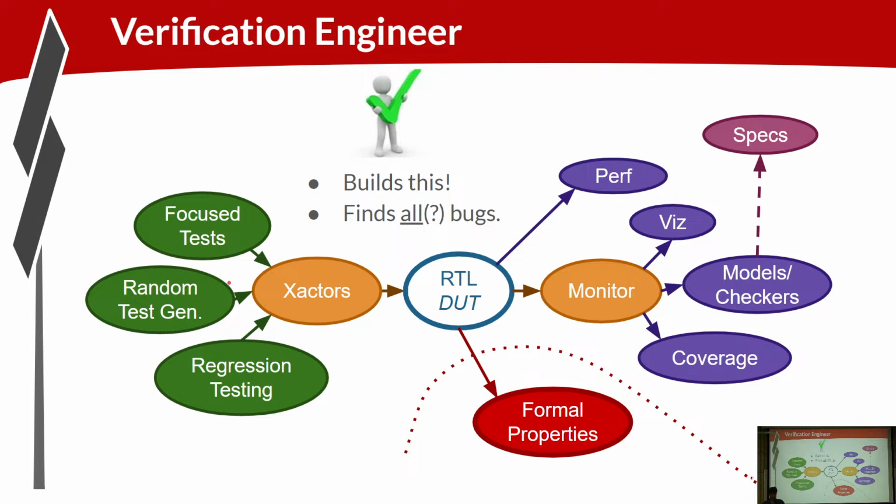And in addition to all this, this would be dynamic verification or functional verification that's based on simulation. We also have formal verification, which is a more mathematical, proof-oriented verification to prove properties about the design. Prove them 100%, for all scenarios, not just for particular simulations with particular stimulus.